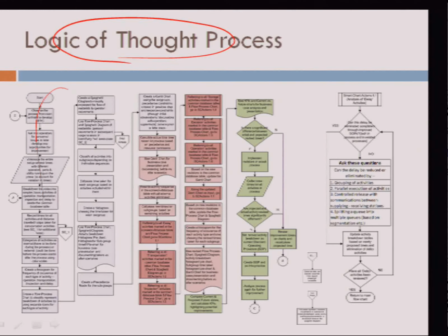So that's what this process really is saying, that once you've mapped the system, once you've observed the system, the first 3 things you should do is try to attack the transportation elements, try to attack the queuing elements, the queuing delays, and try to attack the unnecessary inventory points.